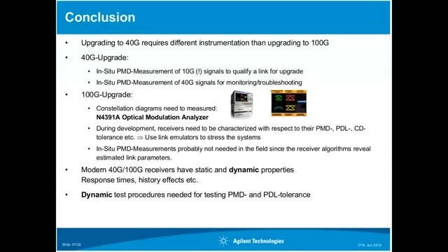Okay. How about this effective DGD you're measuring and have been talking about? Is this considering second order effects? Not at the moment. The second order is at that point, I think, not such a big issue, because you are using the effective DGD to get the readout of the PMD coefficient.